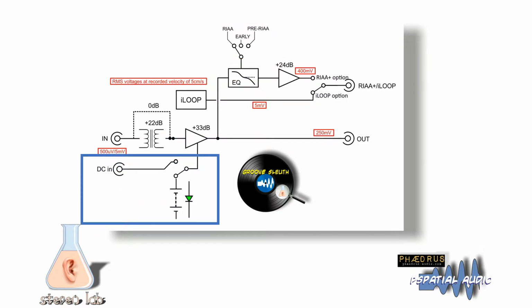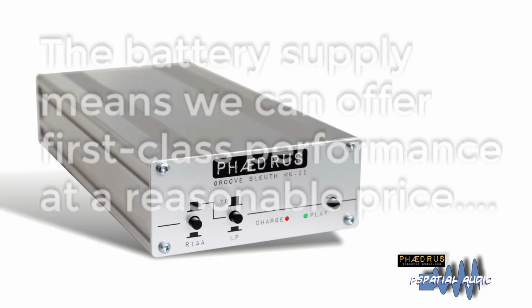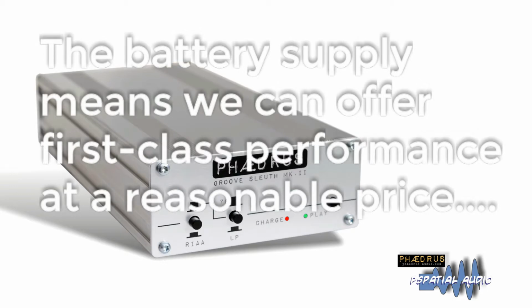Now a further innovation of the Groove Sleuth Mark II is a very low noise battery supply. This means the preamplifier can be powered from a conventional international style power supply, little plug top power supply, but be switched to the battery supply during the needle drops to ensure very best possible noise and aliasing performance. There's a switch on the front panel, you can see on the right there between charge and play, which allows the batteries to be selected, and the green LED indicates the battery health and charge.